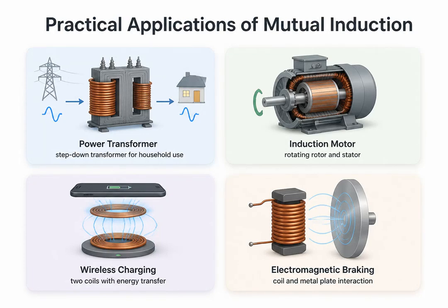Mutual induction is the principle behind numerous everyday technologies. Power transformers step voltage up or down in electrical grids and household appliances. Induction motors use mutual inductance between the stator and rotor to create rotating magnetic fields that drive mechanical motion. Wireless charging systems use mutual induction to transfer energy from a charging pad to a device without physical contact. Electromagnetic brakes use the induced currents in conductors to create braking forces. Understanding mutual induction is essential for anyone working with electrical systems, power electronics, or electromagnetic devices.